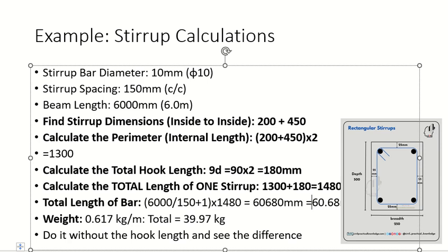So if I tell you that dia 10 steel and dia 16 steel are different materials, then the density will change. Otherwise not. What's my point? Density does not change according to dia. Dia is a size. Density is a material property. So if you take density of cement and put this cement in a bag and then take it out and put it in a different bag, will the density change? No. Mass per unit volume will not change. Clear?